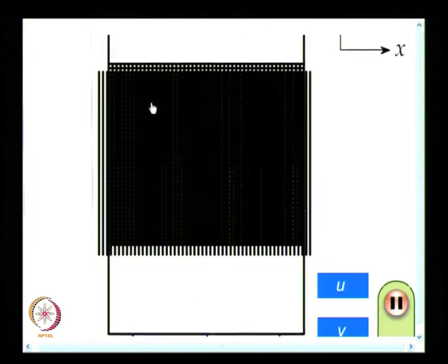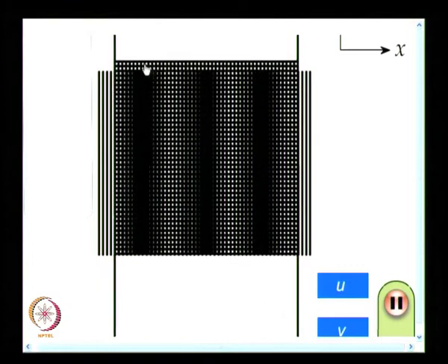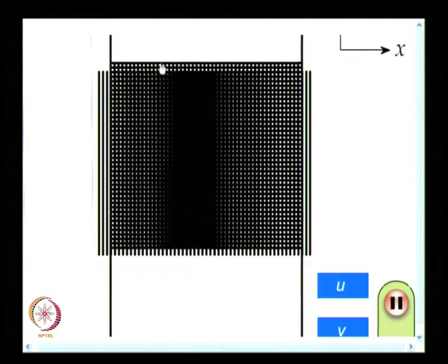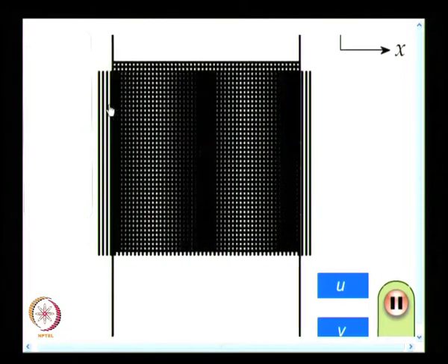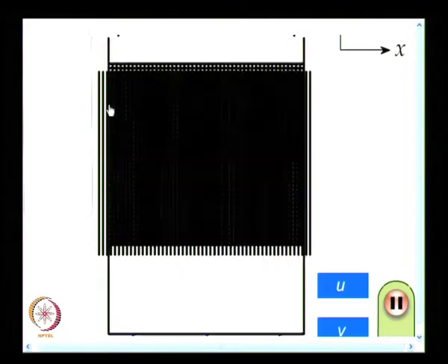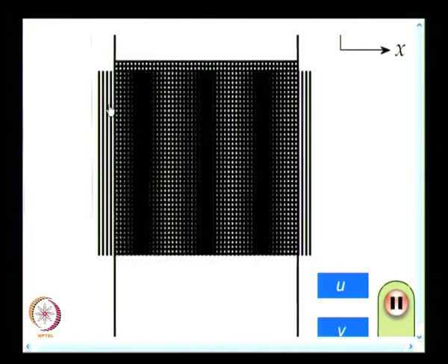So, what I have is, on the specimen I bond only one grating which has a crossed lines, but I view this with a horizontal grating or a vertical grating. So, I can comfortably switch over from U displacement to V displacement. Data interpretation is not difficult. It is very key important, because the next technique we are going to take up is holography.